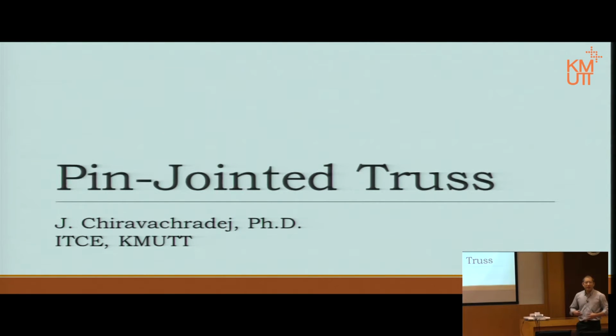Well, there is a certain change of the continuum, but there is no breaking of material, so the joint or the part of material can carry axial force, shear force and bending moment. All kinds of forces can be transferred through the joint and through the section of material. On this structure here, which we call a pin jointed truss, the load transfer mechanism will be a little bit different than what we have done so far. But we will leave that to the middle of the lecture, when we prove the theory and how we solve it later.